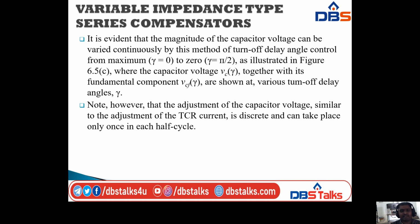It is evident that the magnitude of the capacitor voltage can be varied continuously by this method of turn-off delay angle control, from maximum to 0, that is gamma equal to 0 to gamma equal to pi by 2, as illustrated in the figure. So I will show the diagram, this one.